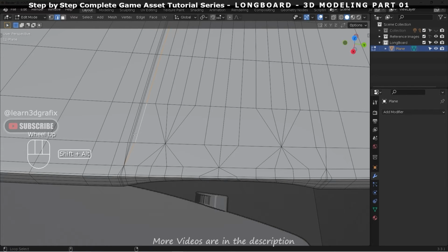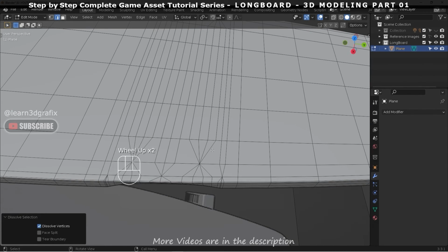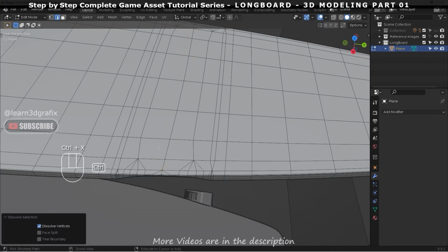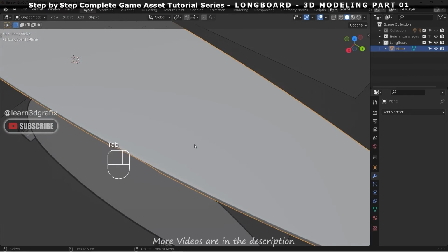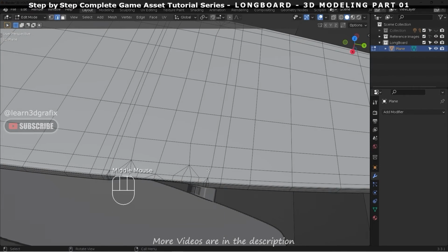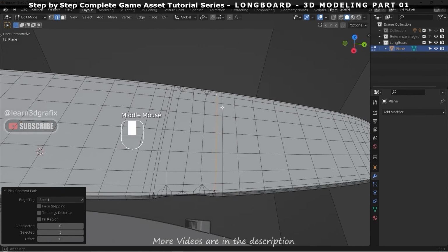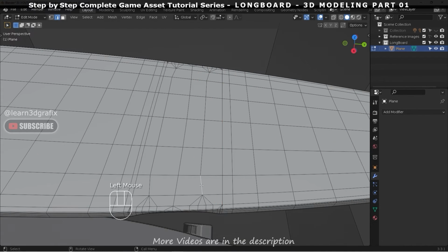Press Alt Shift and select these edge loops and press Ctrl X to delete the selection. Hold down Ctrl and select this edge and this edge. It will select all the middle edges. Press S, Y and 0 to make the line straight.